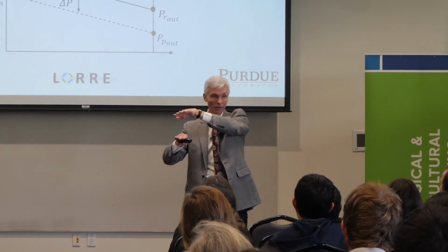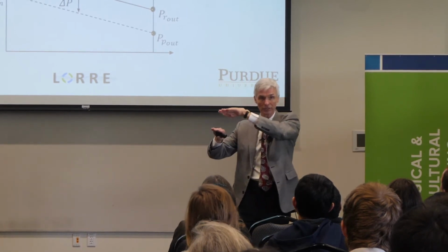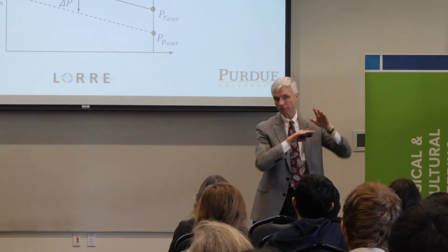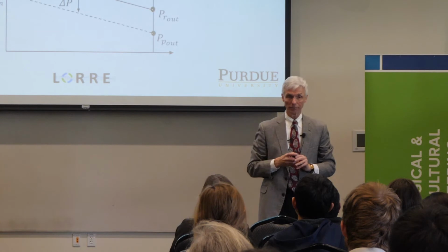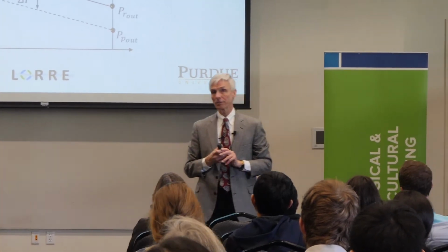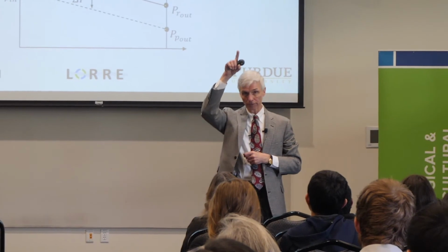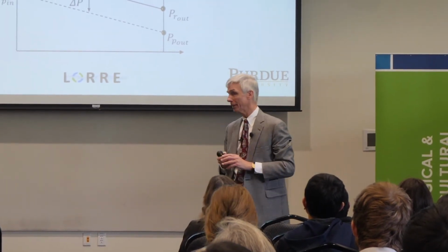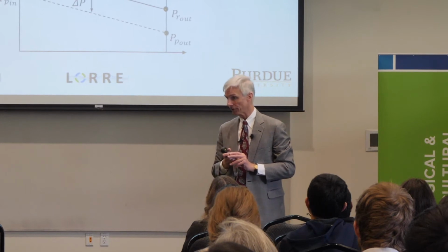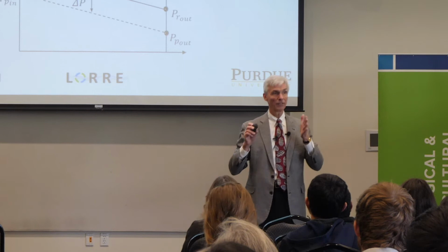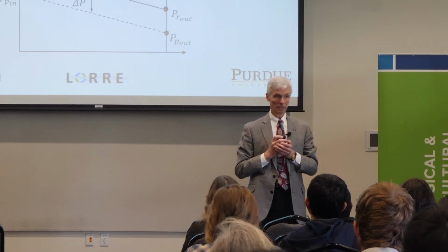Well, things slow down. You don't have enough surface flow, so they start to block the membrane, and then it just kind of goes backwards, and before you know it, you're not able to filter. So what someone else figured out is that by keeping the pressure drop constant as you pass the fluid through that hollow fiber, you're able to minimize this other cause of fouling. So the way we did it is we have flow on both the inside and the outside of the hollow fiber.